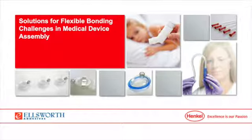Okay, great. And Dee, this next question is for you. How do adhesives perform with materials that contain high levels of plasticizers? Oh, thanks, Molly. Yeah, plasticizers are often used in, for example, PVC tubing that we spoke about previously. And occasionally, again, depending upon the amount of plasticizer, an isopropyl alcohol wipe can remove the plasticizers on the surface. But over time, migrating plasticizers can find their way to, of all things, the adhesive, and that could compromise the